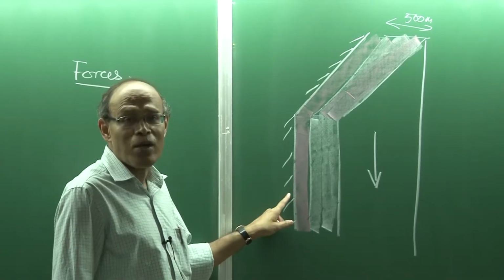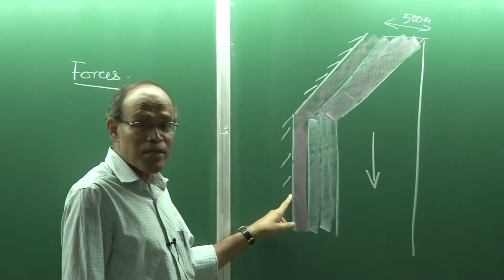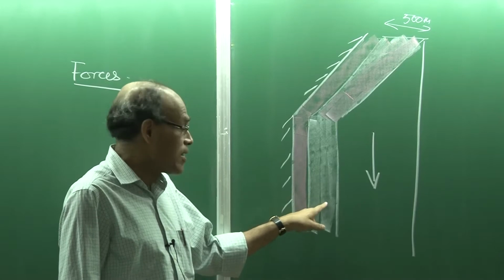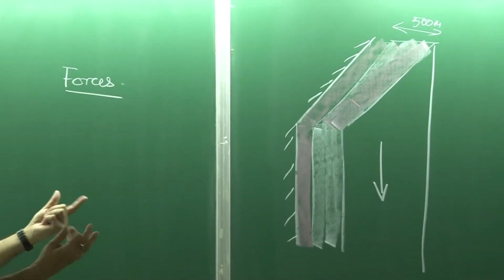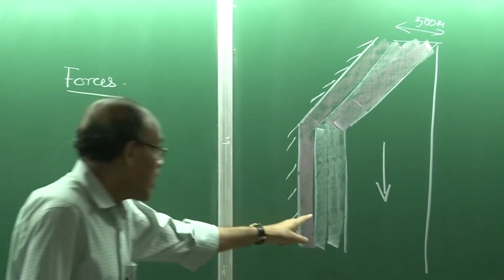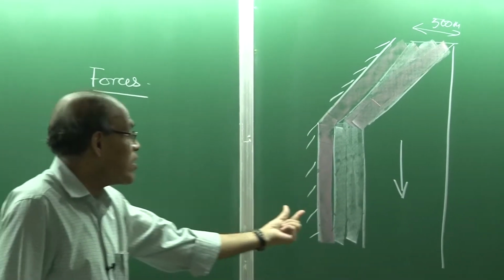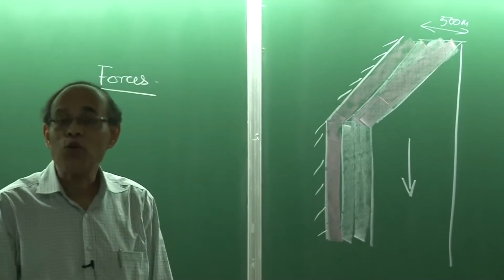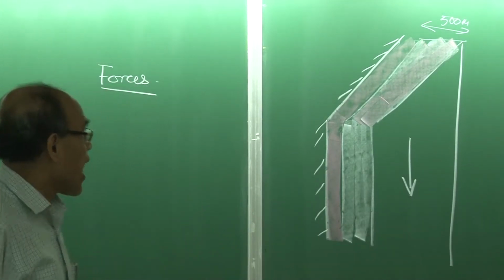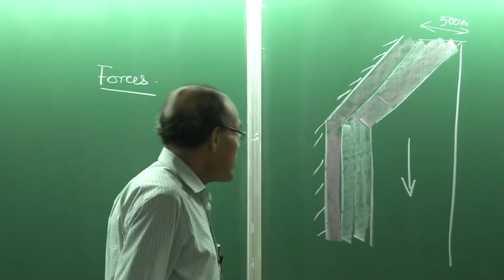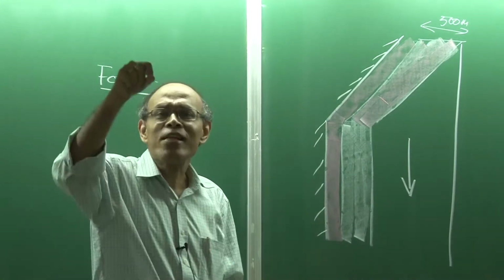It is a very cold mold, at a much lower temperature. The surface temperature here is 700 degrees centigrade. It is here about 1000 degrees or maybe 1200 degrees centigrade at the surface, depending on the location. So there's a tendency of sticking, and to prevent that sticking, we have mold powder that flows in the gap between the solidifying metal and the mold. Now, this more or less flows like a thin film.